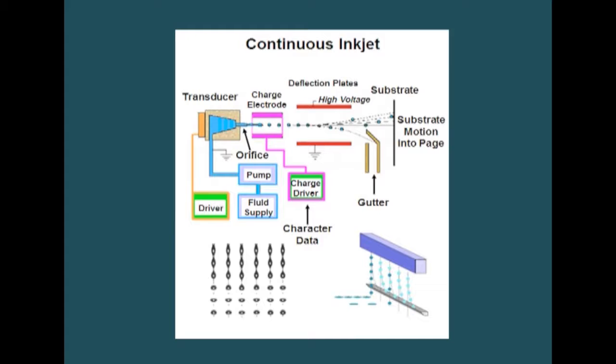The other method employed is the continuous inkjet fabric printing method. In this method, the ink is constantly pumped out through a nozzle attached to PZT material, which generates an inkjet. The nozzle shakes when electrical power excites the PZT material, breaking the inkjet into droplets and allowing it over the substrate.